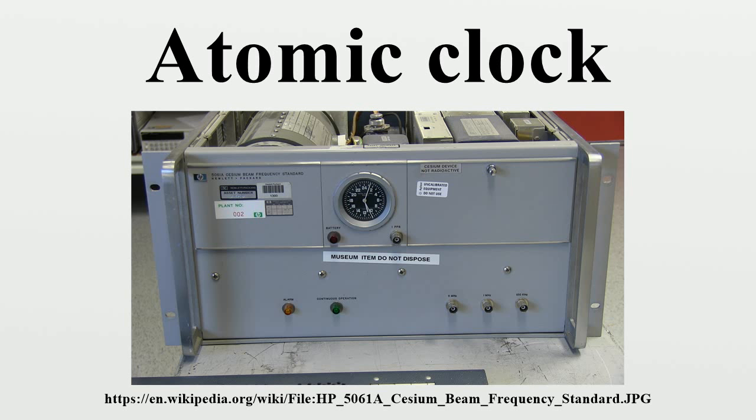Among the significant frequency pulling mechanisms inherent to the gas cell are wall shift, buffer gas shift, cavity shift and light shift. The wall shift occurs as the gas bumps into the wall of the glass container. Wall shift can be reduced by wall coating and compensation by buffer gas. The buffer gas shift comes from the reference atoms which bounce into buffer gas atoms such as neon and argon. These shifts can be both positive and negative. The cavity shift comes from the RF cavity, which can deform the resonance amplitude response. This depends upon cavity center frequency and resonator Q value.